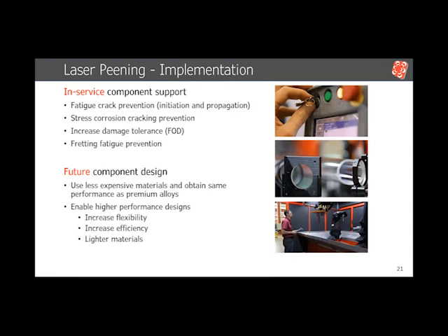Can I use laser peening, for example, to replace maybe an expensive premium alloy? Can I use engineered residual stresses to increase the flexibility and durability of the component while maintaining some level of weight efficiency or lighter materials? Because in the aircraft industry, that's an important part. But I also think that's an important part in the maritime industry, in the transportation industry. So being able to leverage engineered stresses and using our design engineering capabilities is an important element to moving it into the future.